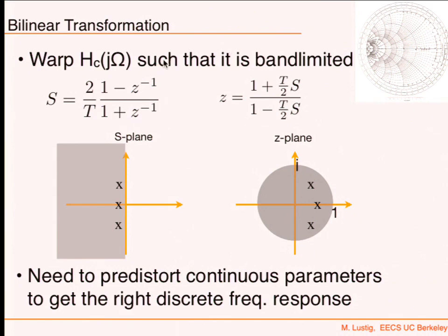Okay. So this transformation basically tells you that you map the complex plane of the Laplace transform onto Z. And what you see is that it satisfies that the left-hand side of the plane will be mapped inside the unit circle. Now, you can't map something that's rectangular and infinite into something that's finite and circular, right? The mapping is going to be distorting. You have to distort things in order to do this.